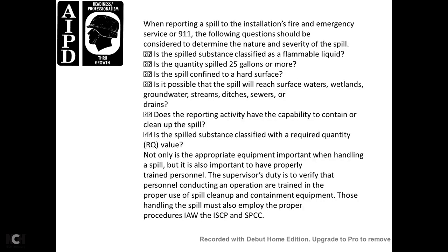When reporting the spill to the installation fire and emergency service at 911, the following questions should be considered to determine the nature and severity of the spill. Is the spilled substance classified as a flammable liquid? Is the quantity spilled 25 gallons or more? Is the spill contained on a hard surface, or will the spill reach the surface of water, wetlands, groundwater, streams, sewers, or drains?